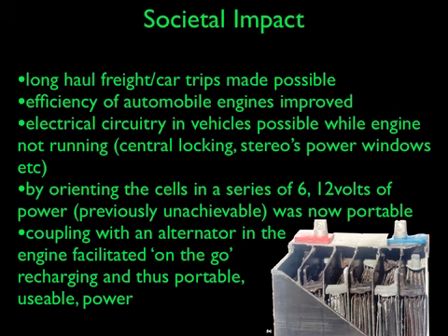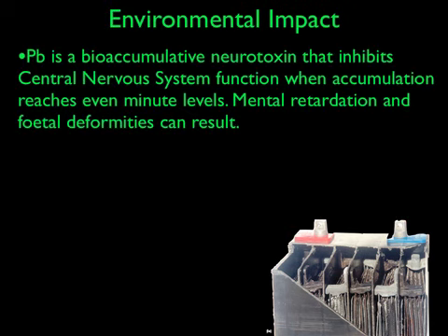As mentioned, you can recharge this battery, and you've seen the YouTube video that describes that, but all that happens is that when the car is in motion, the overall power that's being generated by the combustion reaction can be harnessed somewhat by an alternator, which reverses the poles on this battery and forces the reactions that have happened to the generation of power to reverse, and therefore lead is reformed in the place of lead sulfate, and lead oxide takes the place of the lead sulfate on the other electrode, and therefore these reactions are reversed.